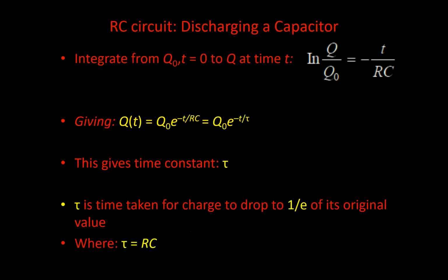What we quite often care about when we have a capacitor holding charge is how long that charge will take to flow out of the capacitor and into the device of interest. If we have a flash bulb, we want to know what order of seconds, for instance, that flash bulb will light for. We don't want it to stay on for too long, but on the other hand, we want it on long enough to give us a good flash to get our photograph.